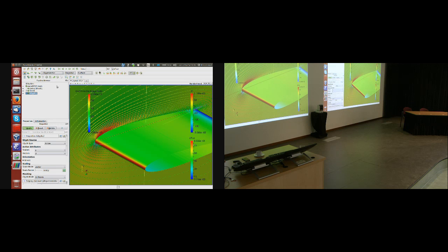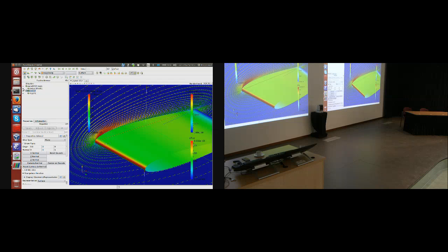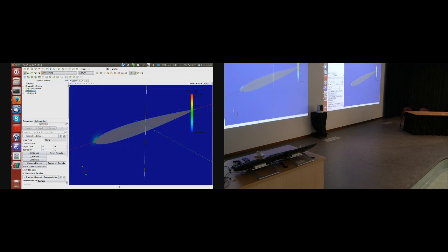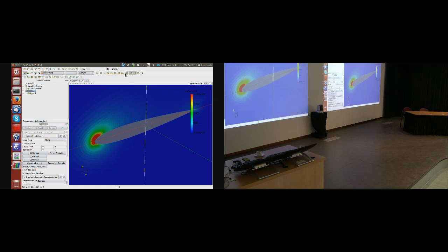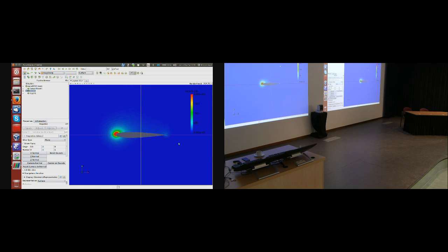Now if I change the time step again, here among the fields on the slice I also have mag grad p. Let's get rid of some of this other garbage and rescale. So my mag grad p is really big here, but I can change the maximum to be 2000, and now the whole thing looks a bit prettier.